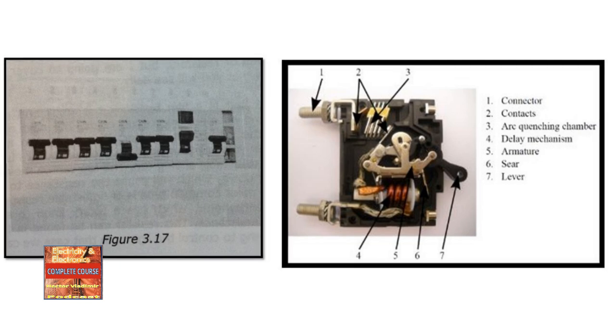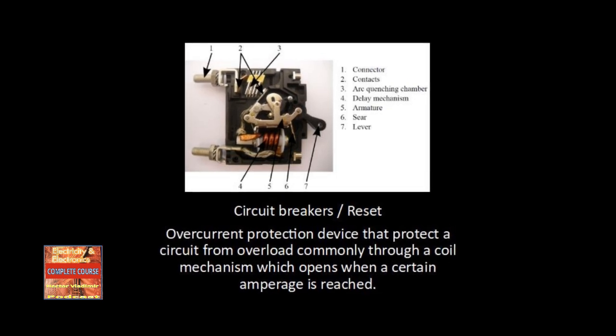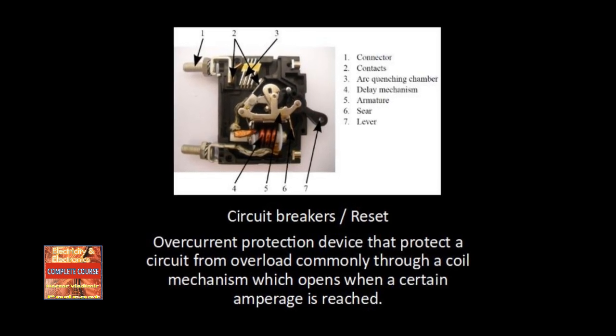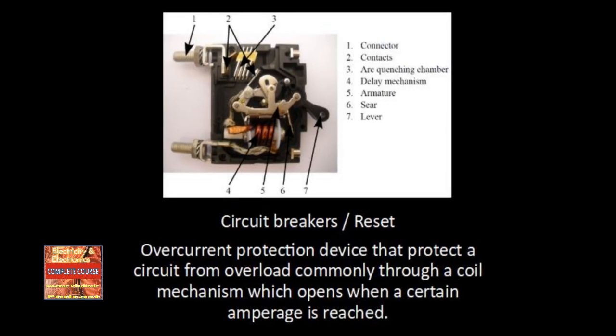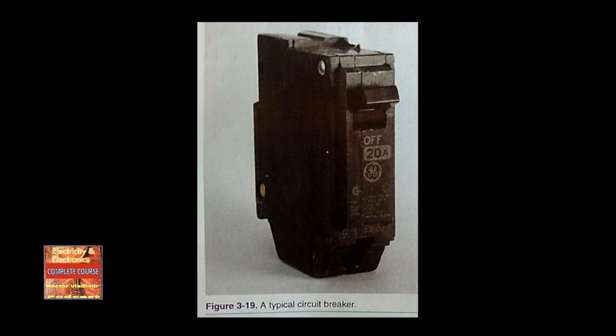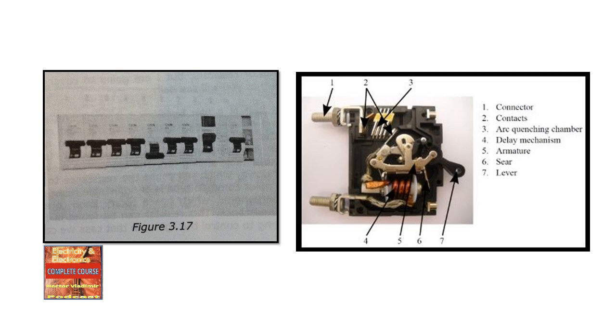There are two ways the circuit breaker can trip, and they are designated by the way they trip. One uses bimetallic strips and the other uses magnetism through coil current, or magnetic. The magnetic breaker is more accurate and costs more, but it is more widely used in the industry. In some homes built prior to the mid-1980s, fuses were used to protect the circuit, but all homes built today use circuit breakers. That protection includes a lighting circuit, which brings me to the next topic, lighting.